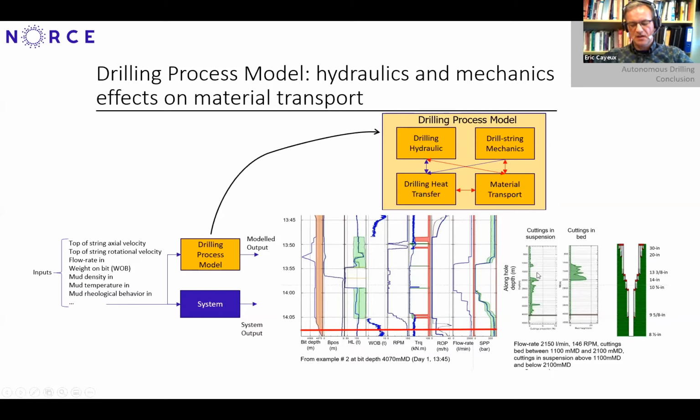and therefore transported again. So you see that even though we have the same conditions as when we were doing the friction test, the results on the transport of the cuttings are quite different because the sequence of operation is different. So it shows that cutting transport is a non-holonomic process. That means that it depends on the sequence of actions that has been applied to be able to estimate how it is working.